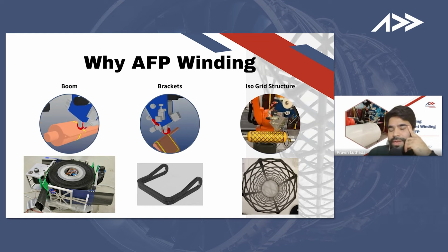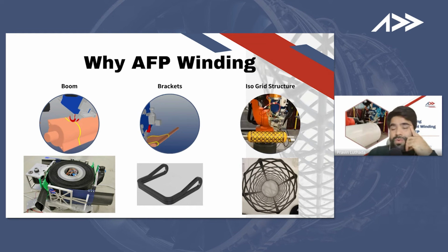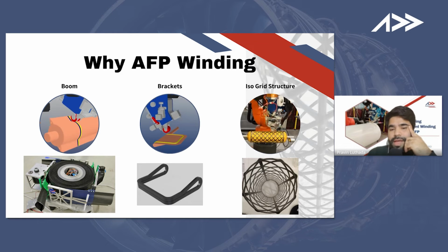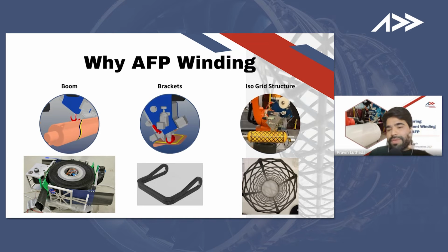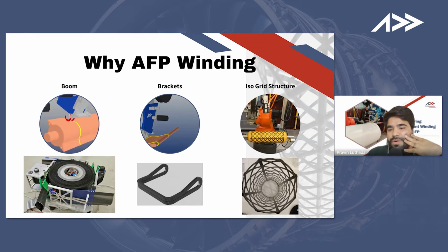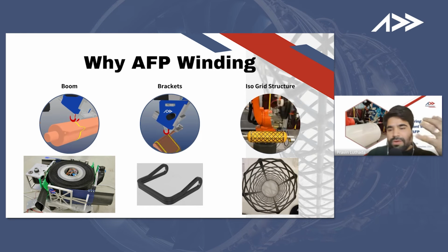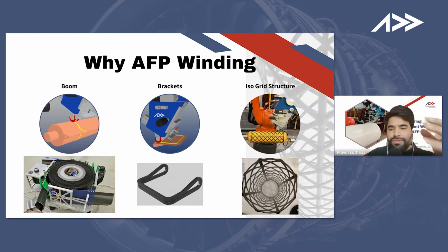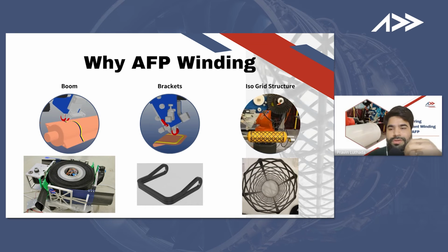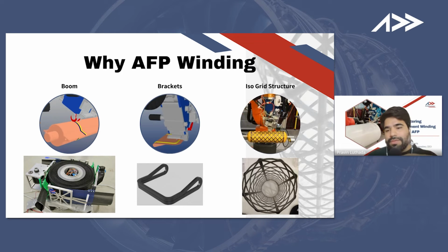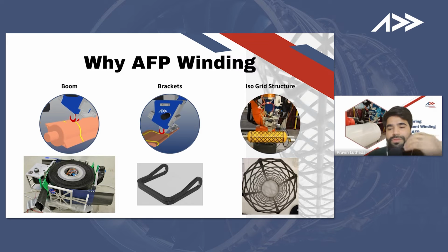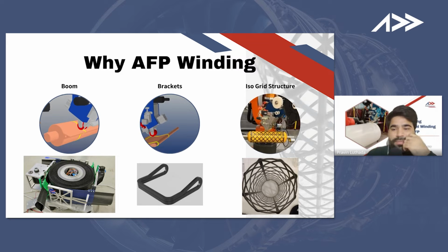And then there is the vice versa benefit. So with filament winding, you're able to do hollow winding where there is no mandrel or physical mold, and then you utilize AFP on top of it. So overall, the combination is only limited by your imagination, like what structure the needs are for the manufacturing of the structure, and then you're able to come up with a solution that basically brings the best out of both processes.